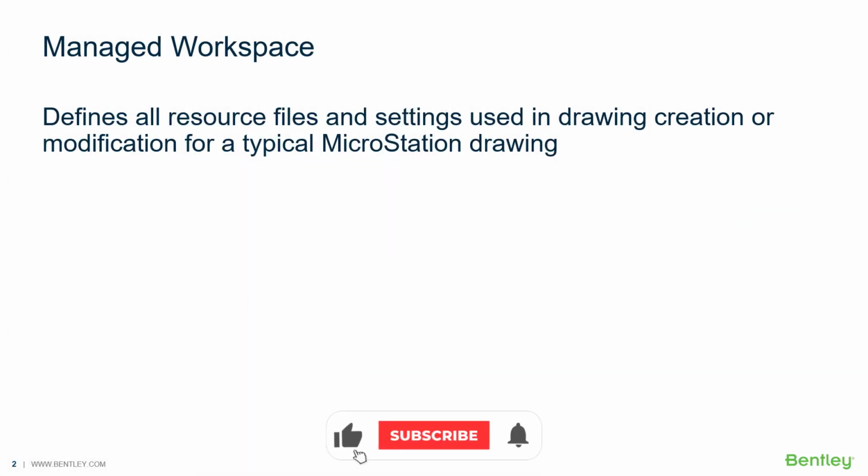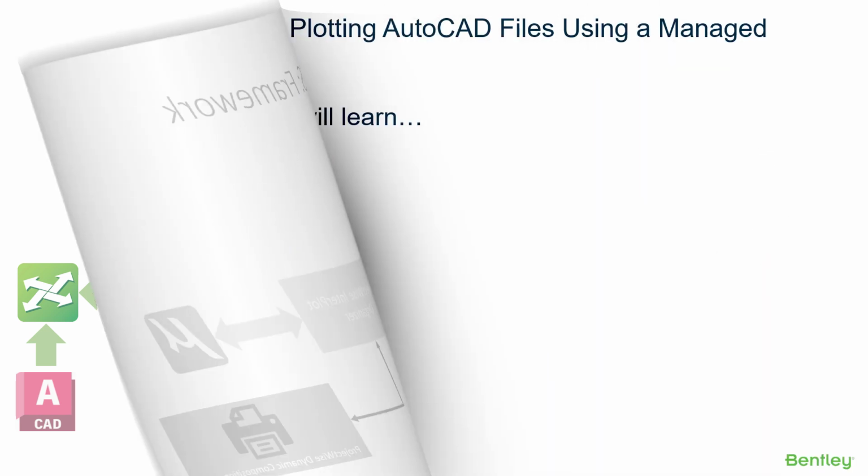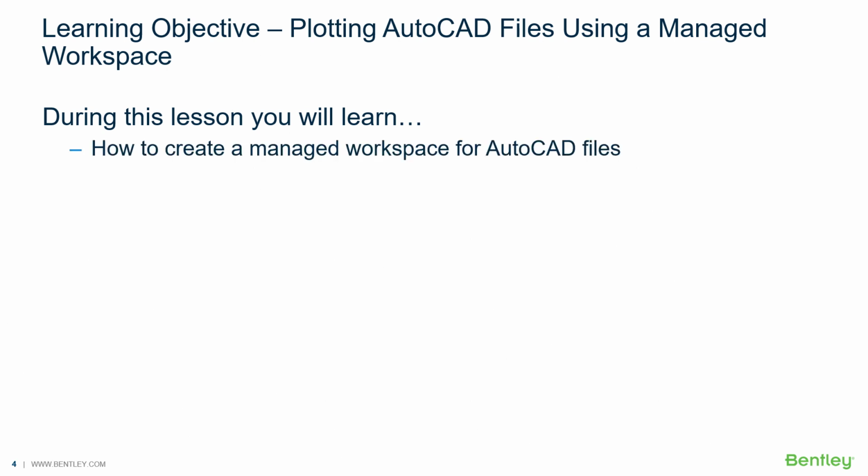A managed workspace defines all resource files and settings used in drawing creation or modification for a typical MicroStation drawing. Now, to be clear, MicroStation managed workspaces do not work with AutoCAD the application, but they are perfect for MicroStation since it is the print engine for the iModel Composition Server. So they are an excellent way of supplying missing fonts and other AutoCAD resources to the print server at plot time. During this lesson, you will learn how to create a managed workspace for AutoCAD files.